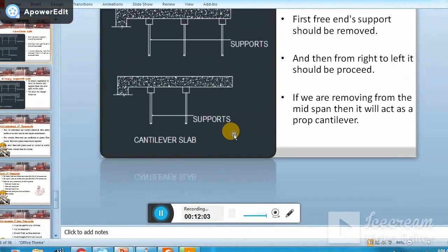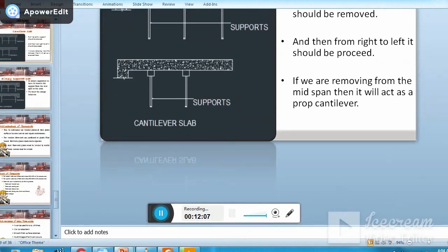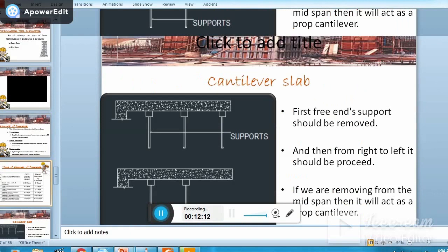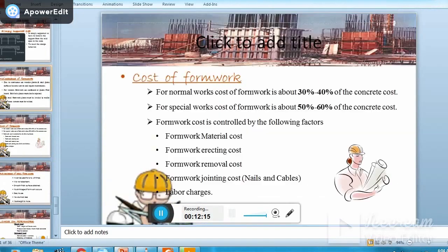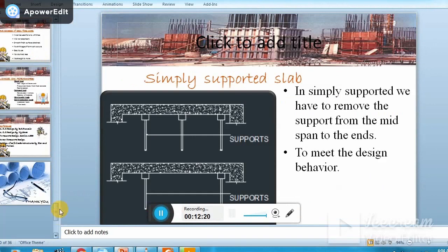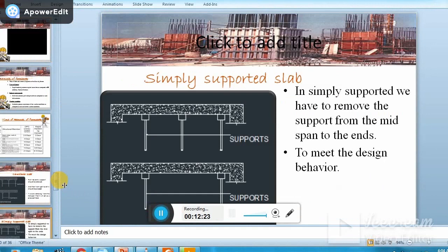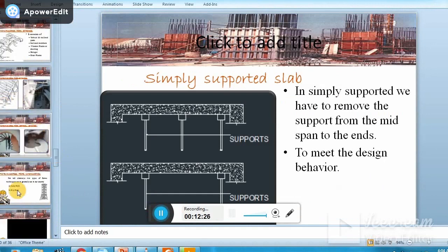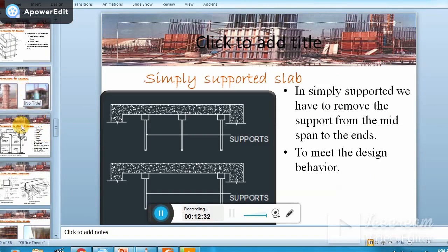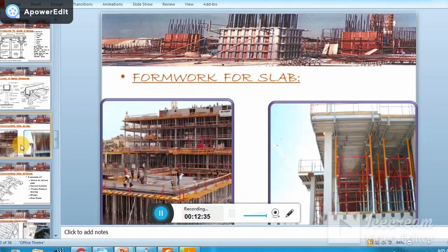There is great advantage of shored concrete. We have different shored construction here. We have one picture that is very important to show you. We almost always provide shoring to concrete structures, because concrete has no capability in the initial stage to support its own weight. So you see all these shorings.